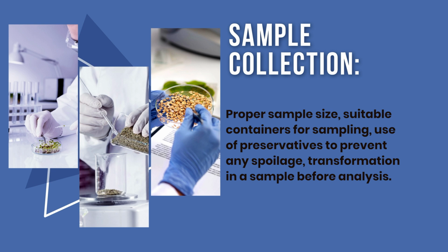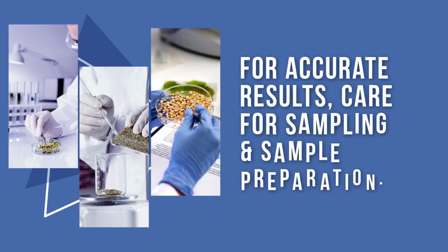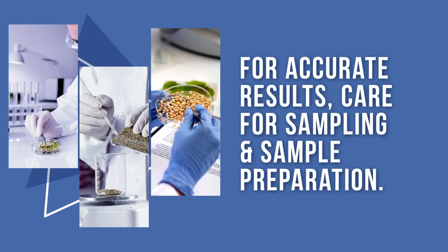Proper sample size, suitable containers for sampling, and how to preserve the sample so that it doesn't get spoiled. How do we transport the sample before the analysis? All that is to be very carefully done so that there is no error at the collection stage. So for accurate results, care of sampling and sample preparation, starting from collection of the sample at the sampling site and then preparation of the sample at the lab site.